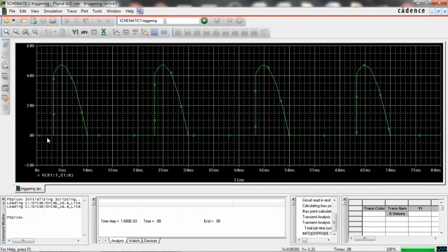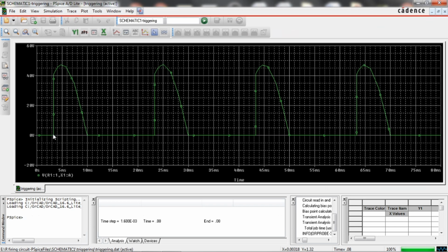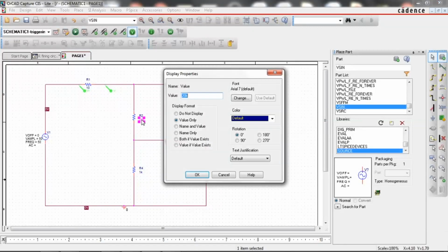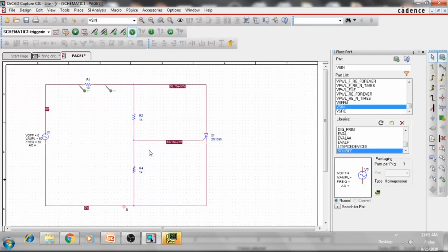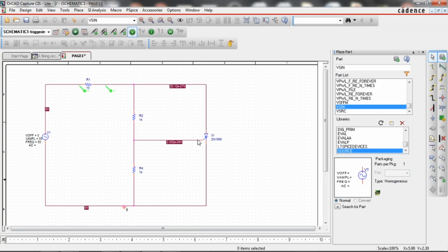So in this way, we can supply a controlled voltage to the load. If you require more voltage, we should keep this firing angle nearer to this. Assume that full voltage is required, and see what happens. I will reduce this to a very small value. See, it is almost acting like a diode rectifier. In the beginning itself we have given enough current to the gate terminal, so the SCR turns on in the beginning itself, and the entire half cycle is passed to your load.